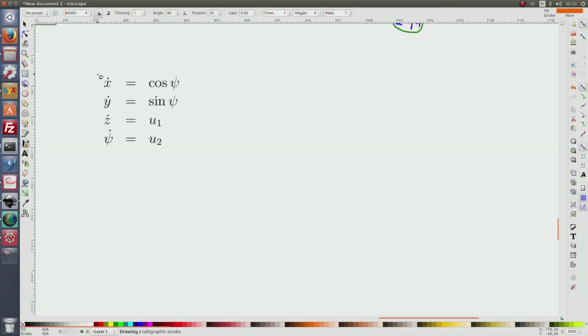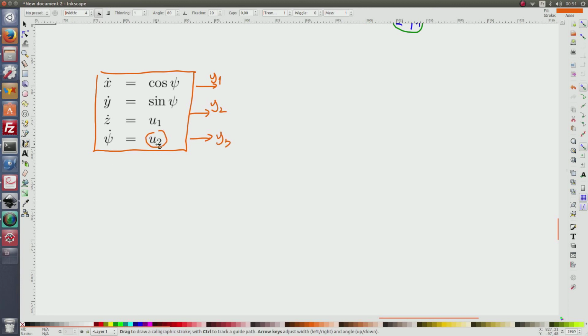So a last remark for our AUV. What we measure here is y1, y2, y3, and for the control of the heading, we use the control we have just explained before, but classical controls that could have been used also, which is very similar, is proportional and derivative control.